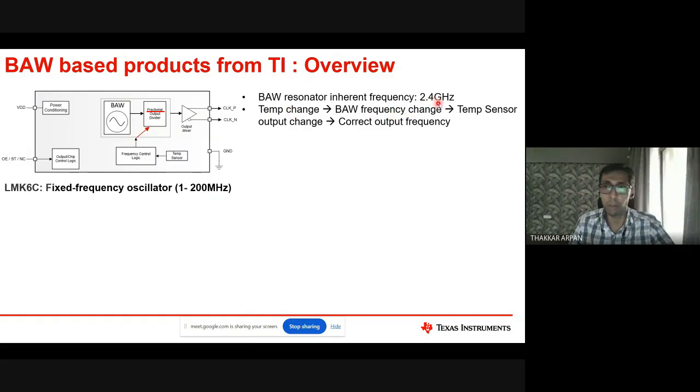So instead of 2.4, it will be 2.39999 or something, right? But we are talking about ppm, about 100 hertz kind of accuracy. For a 10 gigahertz signal, if 10 ppm is the spec, frequency cannot vary more than 100 hertz, right? So many 9s are there, and we still have to maintain that kind of accuracy.